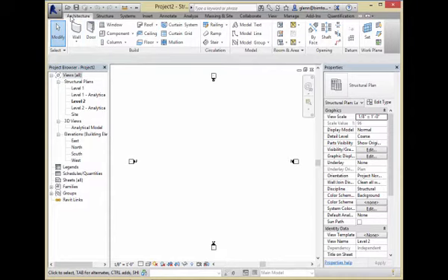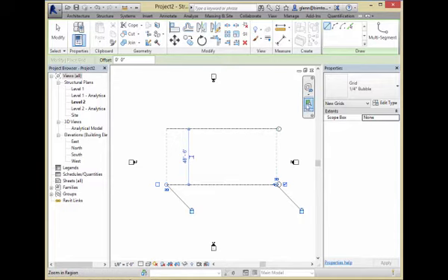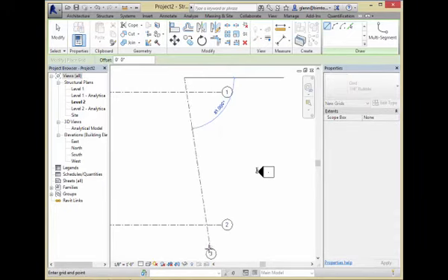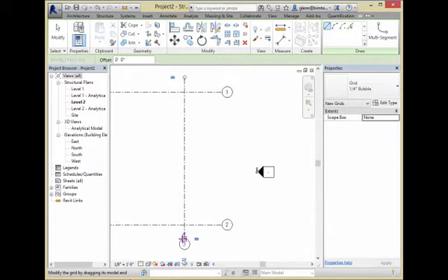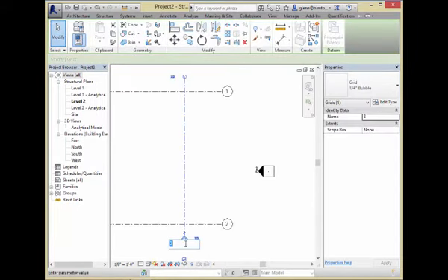In the Revit tool, under the Architecture tab, we've worked with levels before, but I'm going to use something called grids. And I'm just going to draw a grid from left to right. That's going to be grid 1. That's going to be grid 2. So just kind of creating a very simple grid. In the other direction, I'm going to pull on down. Now, it's going to guess 3, because what it always does is it increments. It always goes to the next number. But if I want to switch over to an alphabetic system, I'll just change that to A instead.